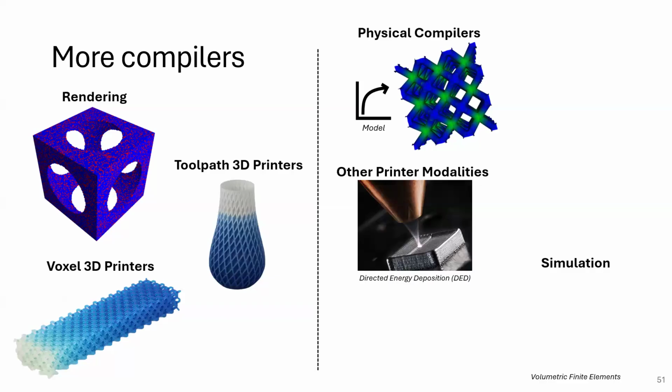If I want to create a gradient across it, let's pretend this white is the hot material and the blue is the cold material. Having a slower transition layer to layer with those temperatures is going to result in better layer bonding than if I try to deposit a hot layer on top of a cold layer. It's about the gradual changes, right?